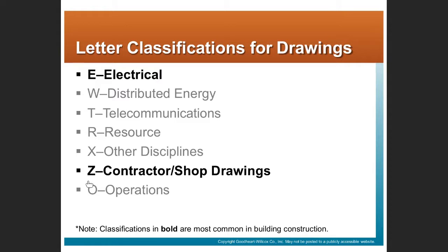The drawings might include these contractor shop drawings, right? Typically, a shop drawing means that the contractor who's responsible for this particular trade may redraw certain things that show additional details. For instance, let's say the structural drawings will show in general terms how the steel is meant to be used to build the building.